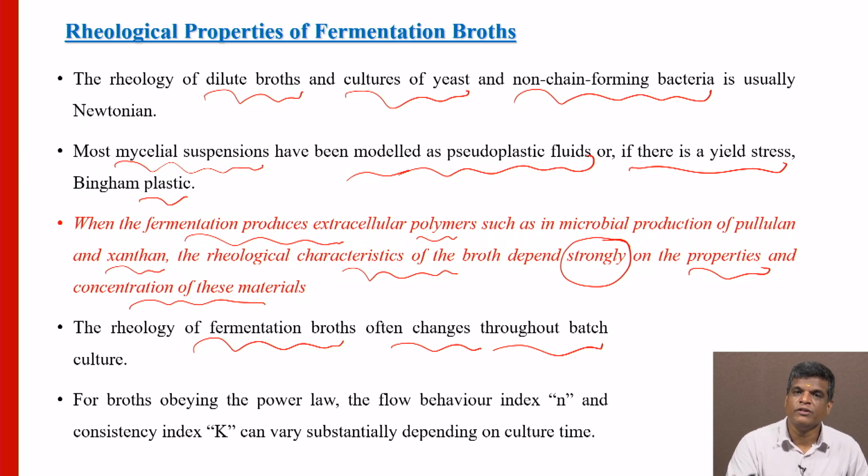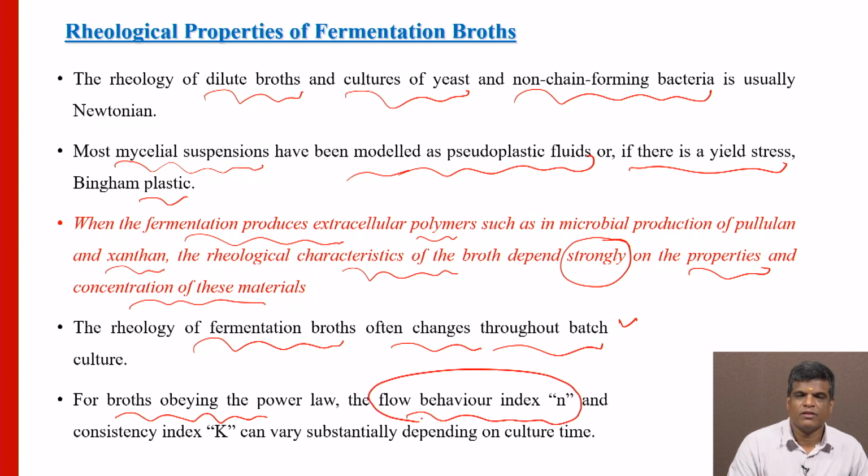It is not just one fixed behavior. For a broth obeying the power law, we have the flow behavior index n and the consistency index K. The flow behavior index n is dimensionless, but K always has a dimension, and both can vary substantially with culture time. That is what we mentioned here.